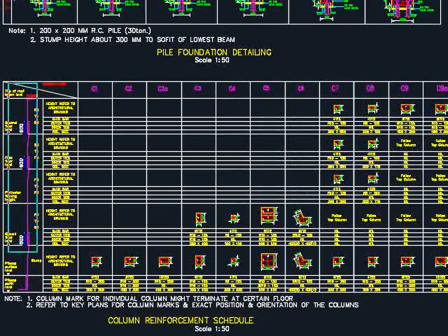There will be a diagram here to indicate the lapping length of the reinforcement bar within the column, especially when you know that the columns are constructed level by level. And there will be illustrations in terms of the amount of reinforcement bar to be provided in the columns, indicating how many reinforcement bars there are, as well as the stirrups that are used to tie the reinforcement bar.